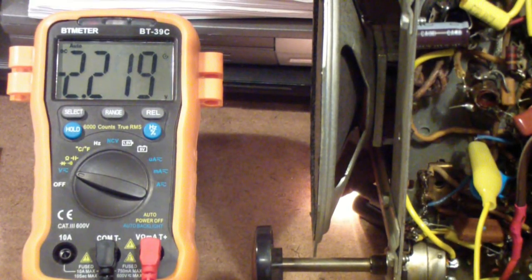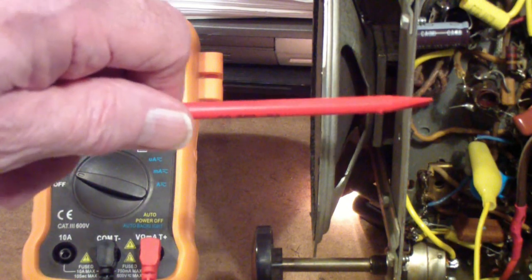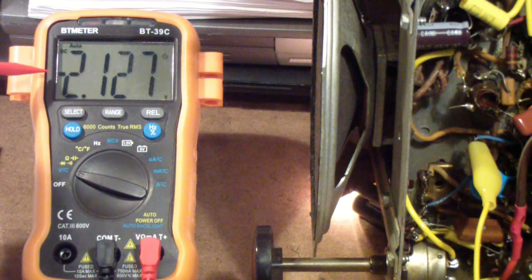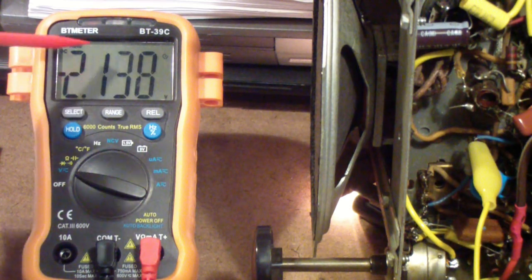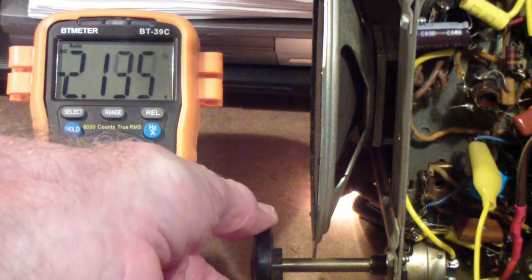Well, this morning, what we are looking at is the automatic volume control voltage in this receiver. We'll talk about that in a minute on the schematic. Notice that we're reading about negative 2.1 volts. It's moving around, and the reason is this voltage is proportional to, in other words, it's a measure of how strong the signal is. So, like I say, we'll look at it on the schematic in a minute, but let me show you basically what's going on. I'm going to turn the volume up.